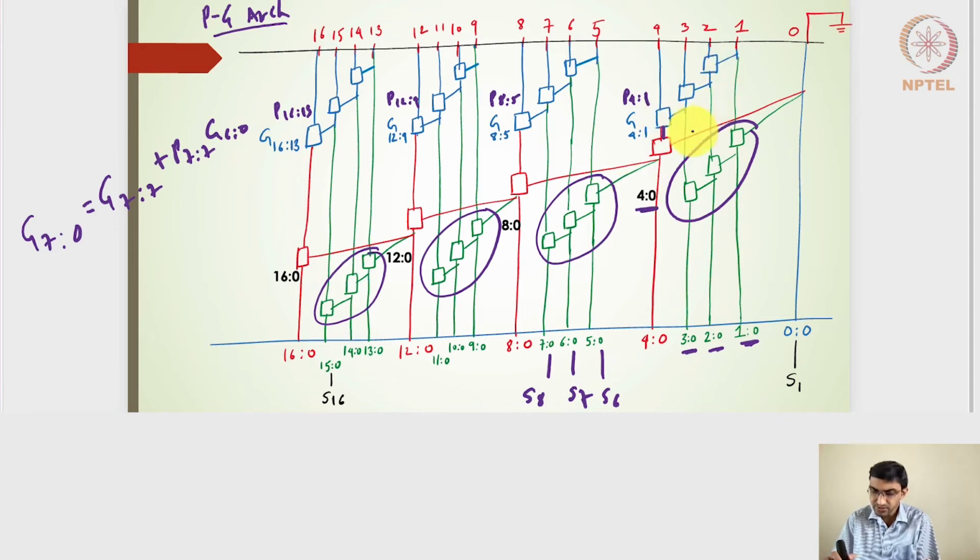Right? Here also it is nothing but the carry ripple, so it actually waits for the previous one and then generates G4:1, G8:5, G12:9, 16:13. Right? So while it is interacting between the subgroups, we have an AND and OR gate, so that we will get directly the 4:0, 8:0, 12:0, and 16:0. Right? Hope this is clear.